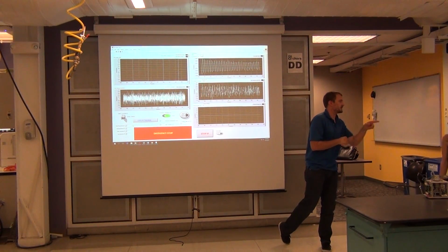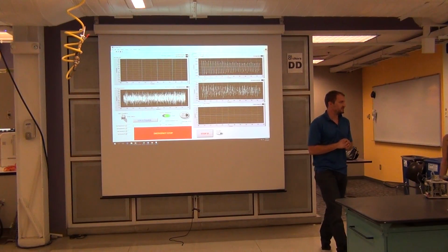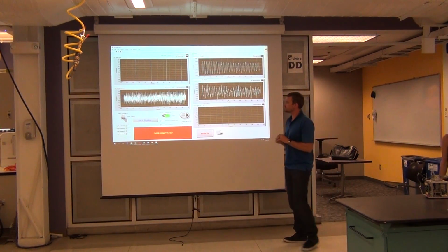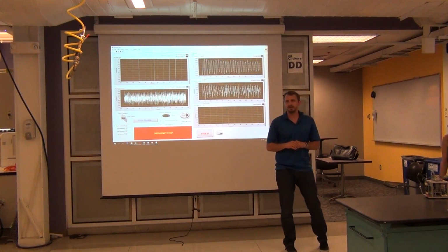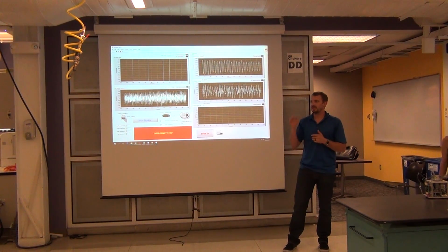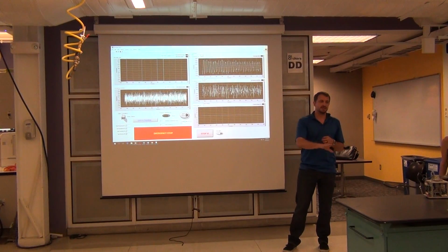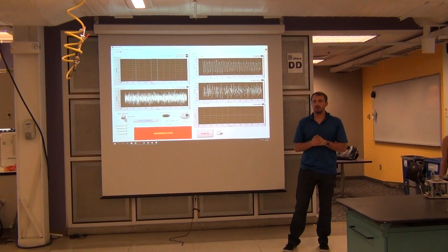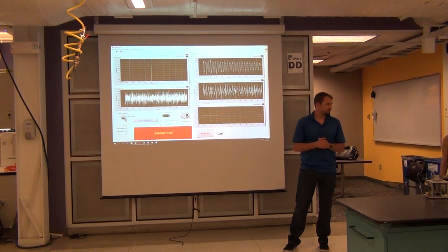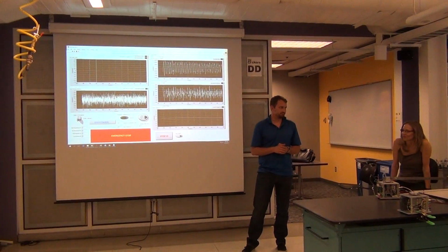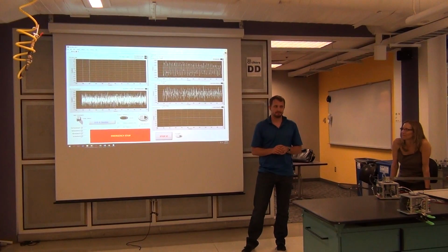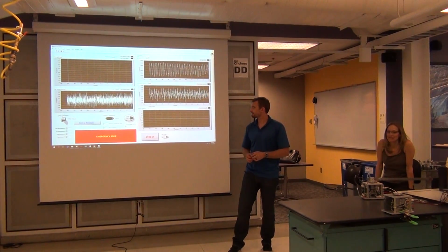Maybe we can take the step off and just do the whole position. So you can see how noisy this hub velocity is, even when we're not moving. So you apply a gain to that, and that noise just then gets fed back into the motor controller. So that's why large derivative gains are not feasible because of the noise. I think that's it.